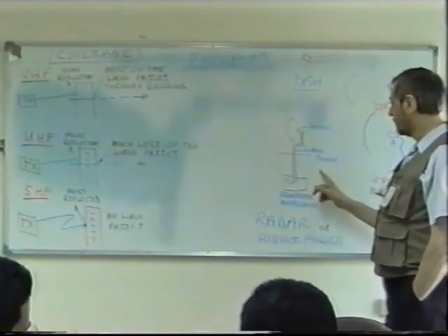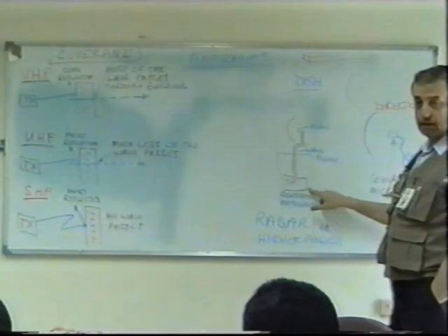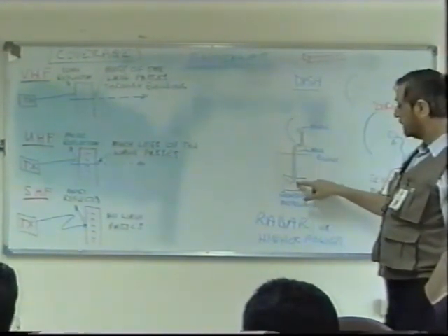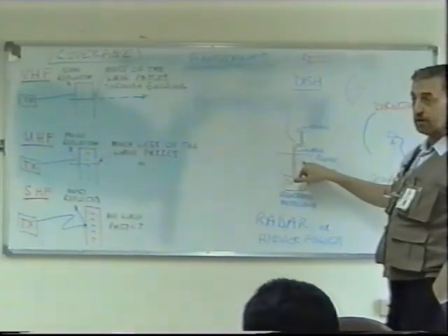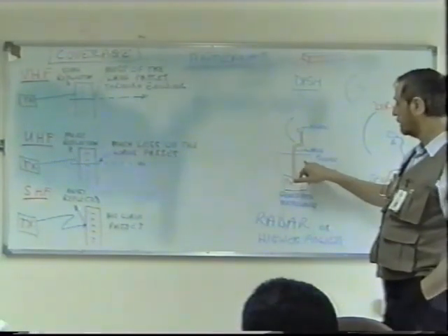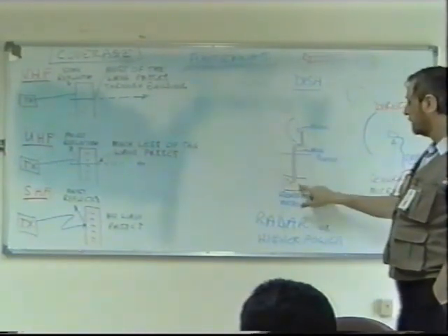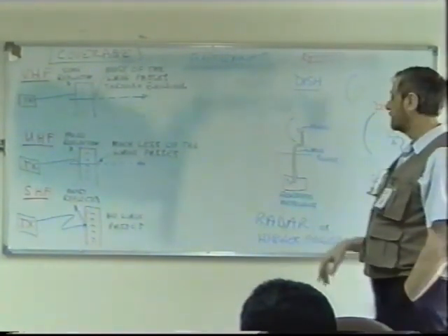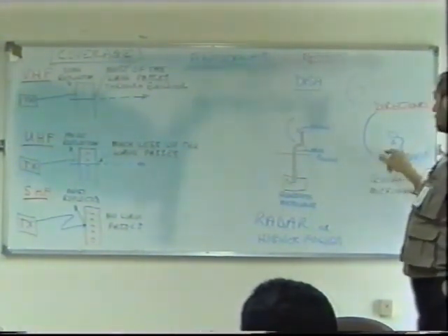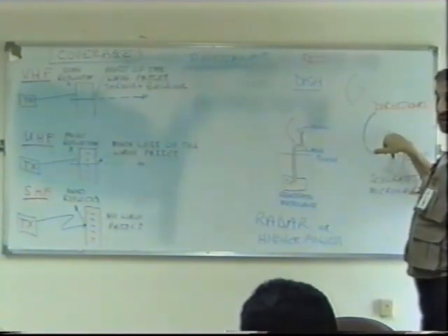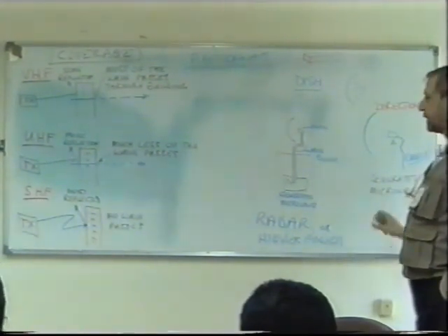I mentioned briefly this morning there are two ways. This way is where we generate the microwaves remotely, and in order to get that signal up to the dish you have to use what is called a waveguide, which is basically a metal tube or metal guide, quite an expensive arrangement, usually used for high power or maybe radar installations. The most common arrangement for communications is this, where the microwaves are generated in front of the dish. They're actually generated here. They're not generated remotely. So you have